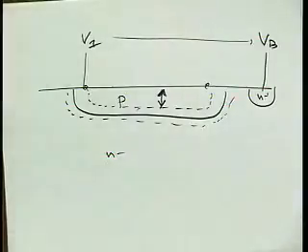Now, you may say, well, then I just use a poly resistor. Well, aside from poly still having a somewhat lower sheet resistance, so that's one reason you may not want to do that, poly also suffers from this effect, because poly is also just doped. It doesn't have a junction there, but if you have a strong field across poly, you get all the carriers to one side, and at some point they're filling all the acceptors, or whatever. They fill up all the states, and then if you want to put more carriers there, well, sorry, this parking lot's full, right?